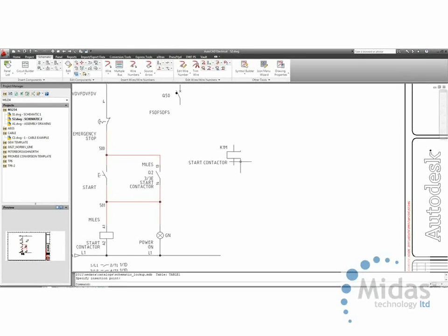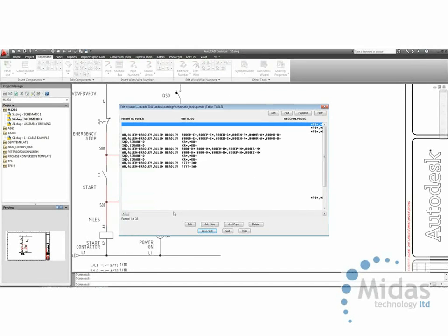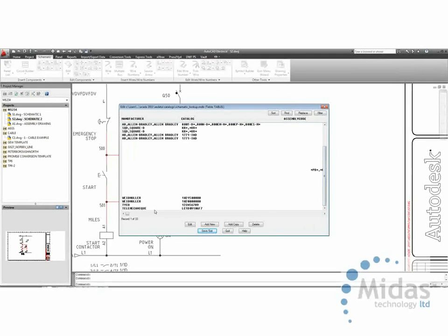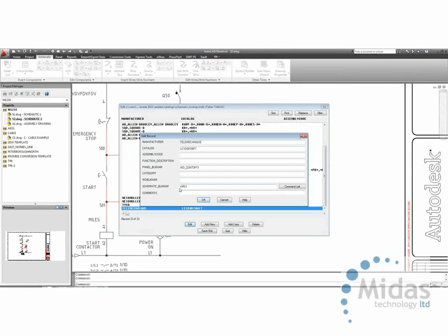So, as I mentioned, that automatically offered me a block called VMS1. When I placed the push button down in the schematic, it automatically offered me a VPB11 or an HPB11 as the option for the switch. Why did it know, and how did it know, which schematic symbol to associate with that particular part? Well, there is what's known as a schematic database file editor, and the schematic database file editor holds that type of information. So as an example, the Telemechanique LC1D09106F7 that we've just placed had a schematic block name of VMS1.